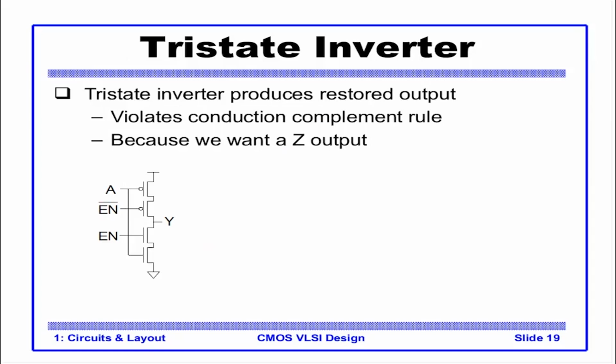Tri-state inverter is a very popular style of logic design. It is used heavily in construction of muxes. Let's see how. And plus it is also restoring. That means the noise is not passed on to the output.